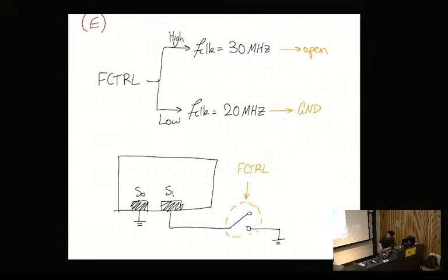Now, you've raised a good point that if I use PMOS, it sounds like a good idea because a low signal needs to pull to ground. But does a PMOS pull to ground? No, only an NMOS will be pulling to ground. So we need some sort of NMOS with some sort of inverting logic to get it working. So first you identify, okay, I need an NMOS, and then as you just did, we work backwards to see how we can deal with that control signal.